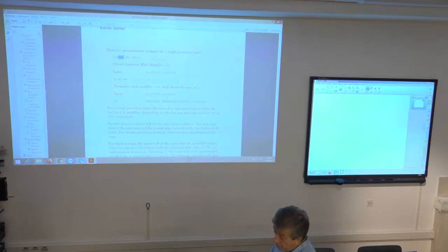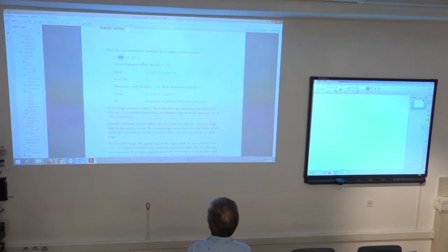This exponent instruction can be applied to the shifter input register, but also to any of the result registers of other execution units. For example, you can take MR1 or whatever other register as input value, and then shift it either relatively high or low.